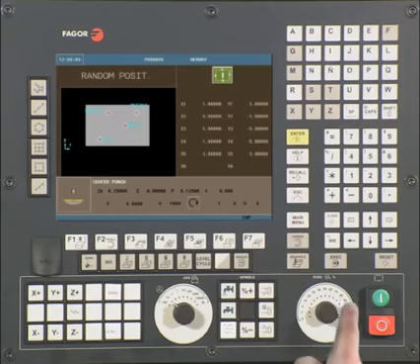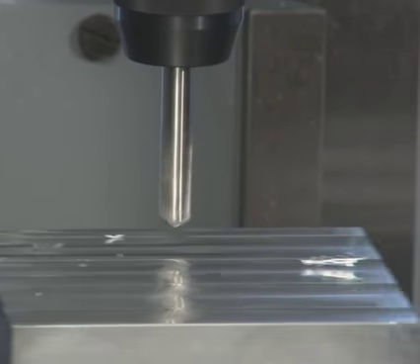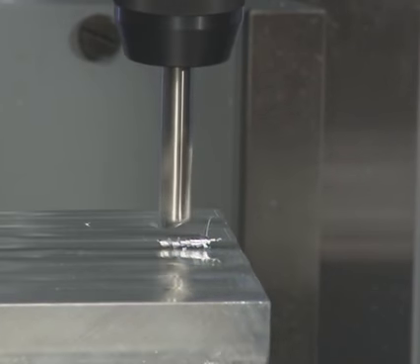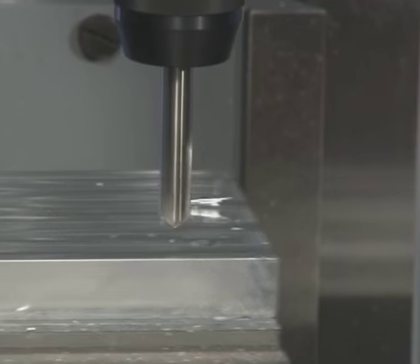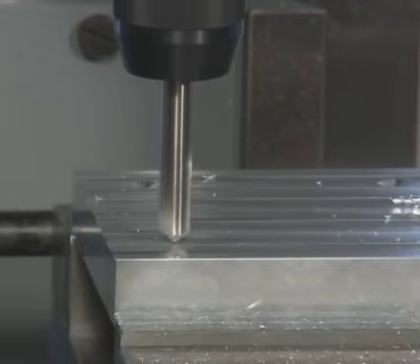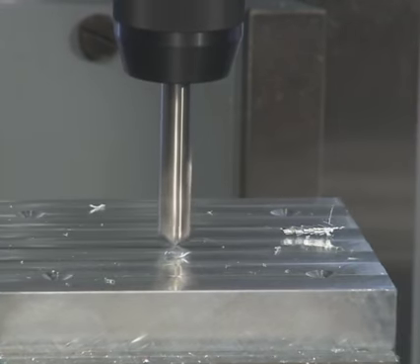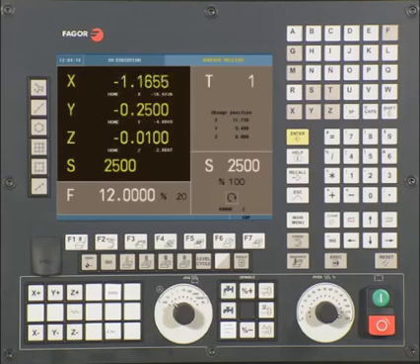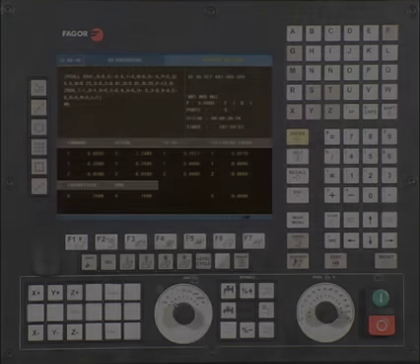Turn down the feed rate to 0 and press Cycle Start button to begin executing the cycle. You will need to increase the feed rate after pressing Cycle Start. If gear ranges are an option on your machine, you may be prompted to change to the correct gear. Change gear and press Enter to continue. Slowly turn up the feed rate so execution can continue. To see additional information while the program is being executed, use the half key to toggle between Basic and Advanced Screen.